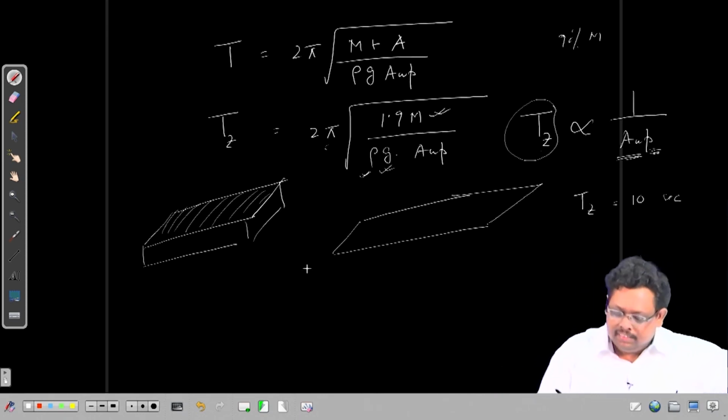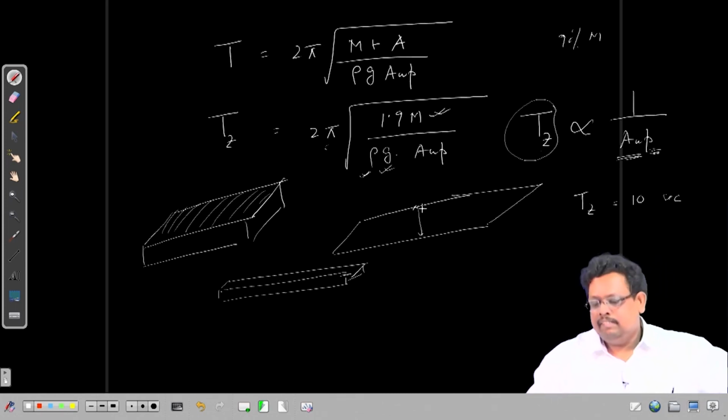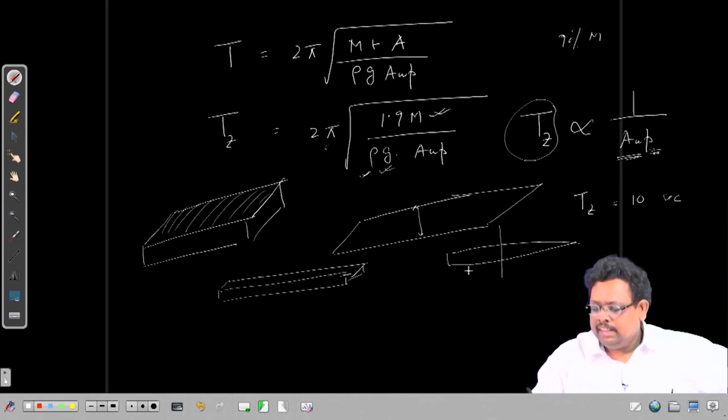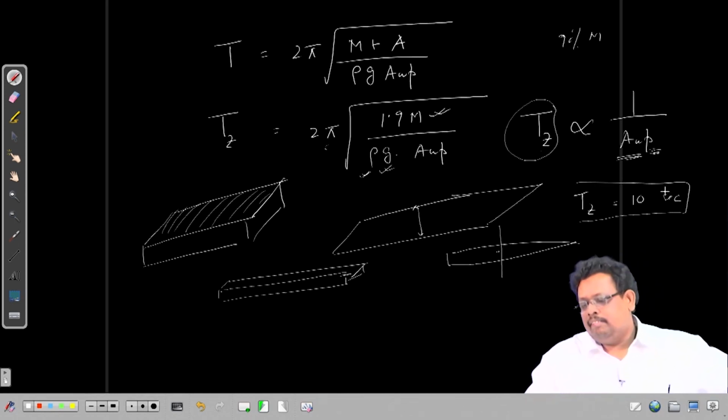But you are not happy, because if your ship becomes slender, you fear it might not be hydrostatically stable, because the restoring moment may be less. To make it slender you compromised with the beam of the ship, so the beam is smaller. In that case the ship may capsize. However, you are getting a very nice natural time period of 10 or 15 seconds.